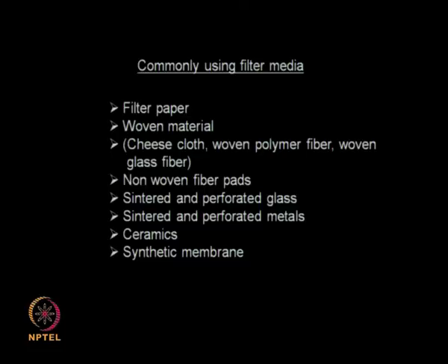it. Sintered and perforated glass, sintered and perforated metals, if the solids are going to be abrasive it is better to use a metal type of filter medium. Ceramics, if you are talking about high temperature filtration, ceramics will be able to withstand these high temperatures. Membranes, synthetic membranes, different types of membranes, hydrophilic membranes, hydrophobic membranes. So all these materials are being used currently.